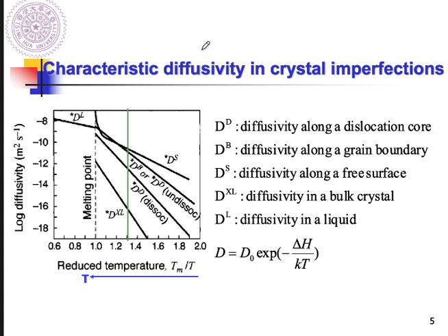So what does this mean? We have a dislocation, for example, with a Burgers vector like this. This is a whole dislocation. This is the Burgers vector. This we call an undissociated dislocation. And for a dissociated dislocation like this, we can decouple this Burgers vector into these two smaller Burgers vectors. Based on this, the undissociated dislocation has higher lattice distortion compared to the dissociated ones.